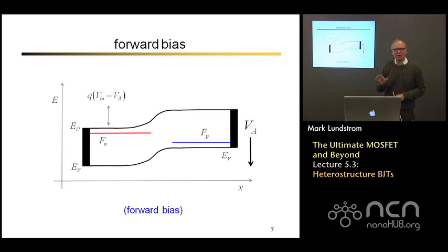We had an energy barrier of roughly the band gap to begin with. And now that we've applied a positive voltage, we've lowered that by a few tenths of a volt, and now we have a lower energy barrier. That lower energy barrier now means that it's much more probable for electrons to hop over the barrier from the N side to the P side. Remember, their probability of hopping over a barrier is e to the minus barrier height over kT.